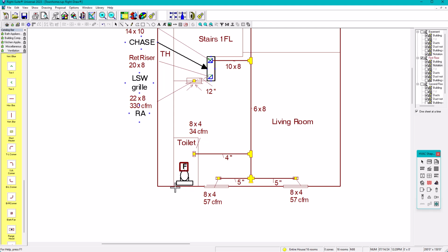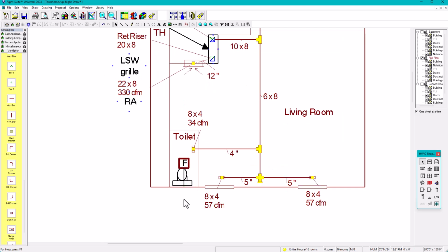The one that is closer to outside is the sidewall. So it's an obvious option and choice to use the sidewall. So we're gonna drag in here duct. There you go. And then what we're gonna do in here is move it to the side so it looks better. Well, maybe I could move this. There you go. Okay, and then I'm gonna represent this as a wall cap. There we go. Okay, so that represents my wall cap.